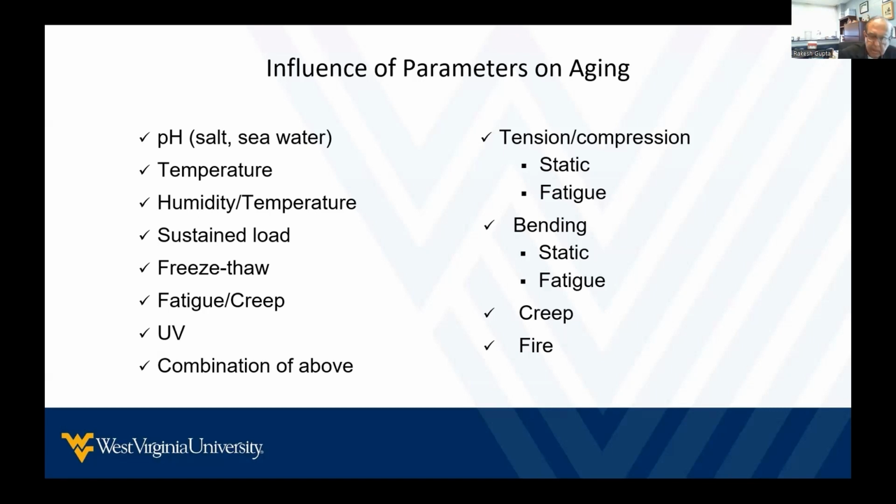In addition, the resin, if it dissolves in the water that has gone into the matrix, it can cause osmotic pressure gradients, and this results in delamination of the fiber from the matrix. So every component of the composite can be hurt just by the presence of moisture.